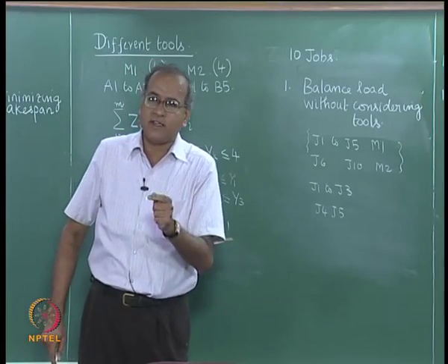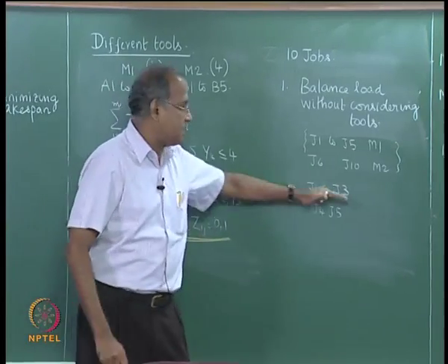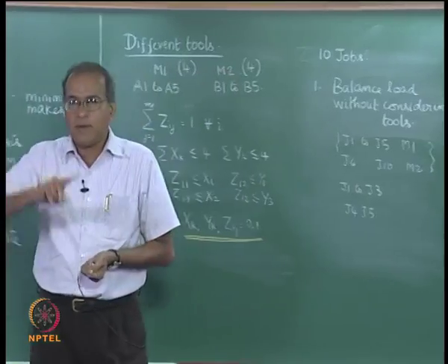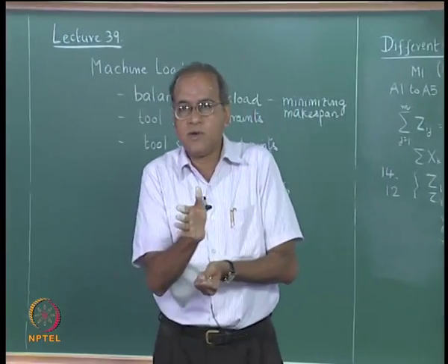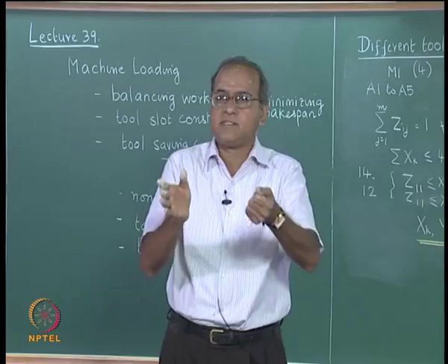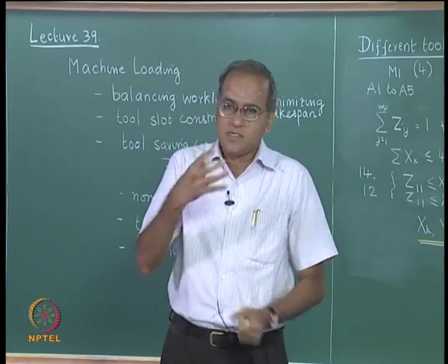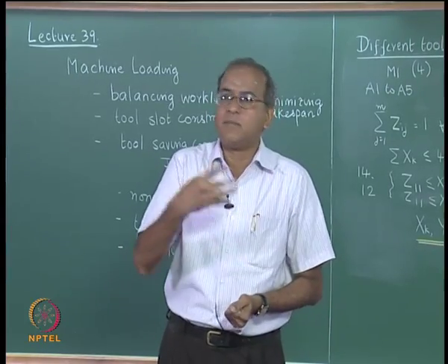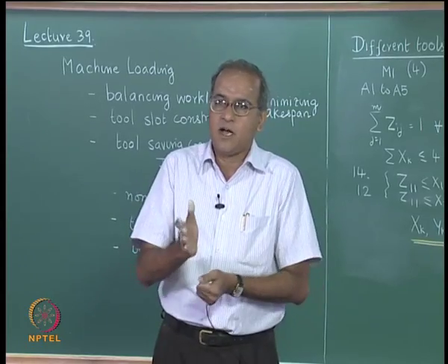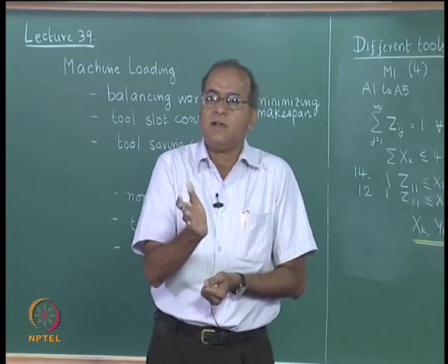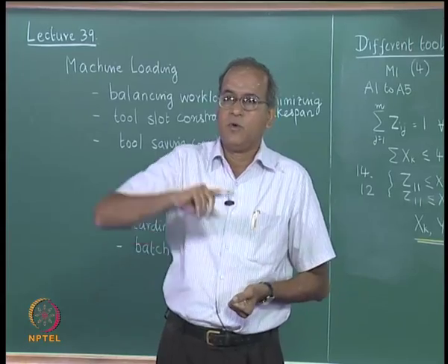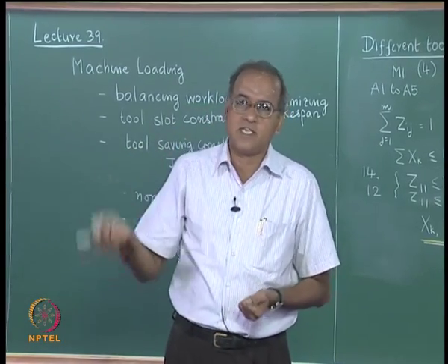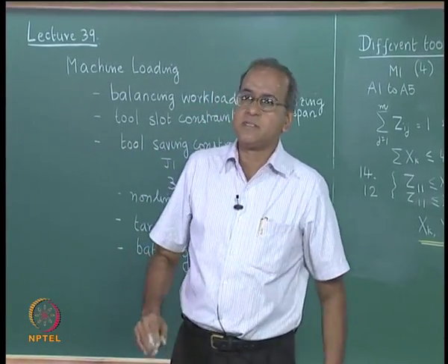The only difficulty there is in practice, if all 3 go in one batch, depending on the sequence, they can actually come out sooner than the batch is completed. The jobs within a batch, they do not come out at the same time. The jobs come out as and when the processing is over. Only the tools are available for a change after the entire batch is completed.